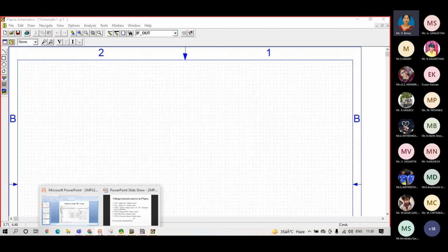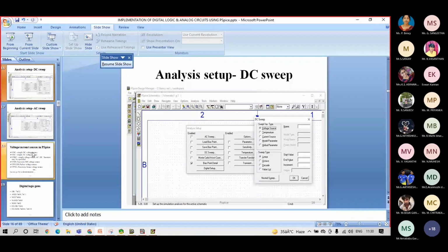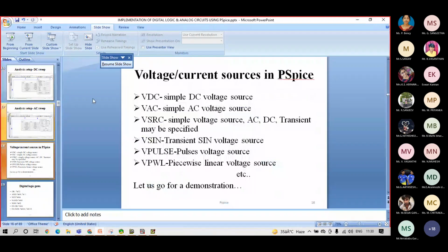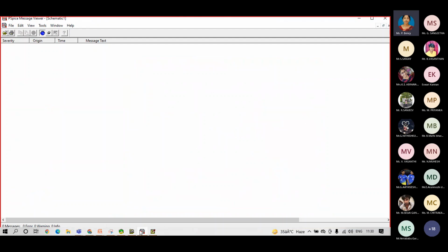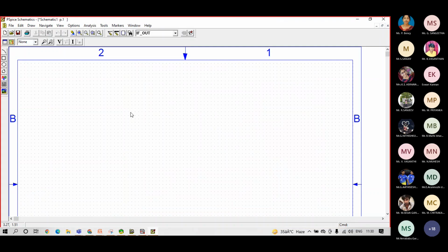So our first voltage source is VDC. Now listen carefully. I'm moving to the simulation tab. You have the get new part option in this particular tab, next to the search bar.